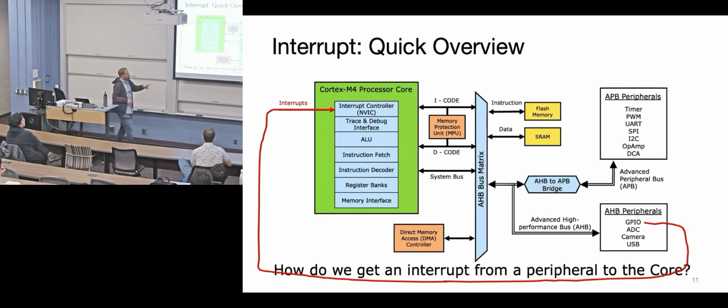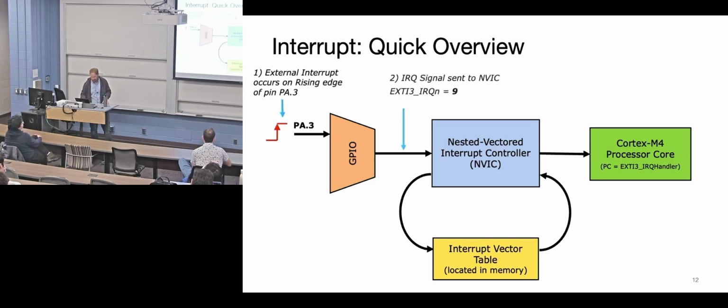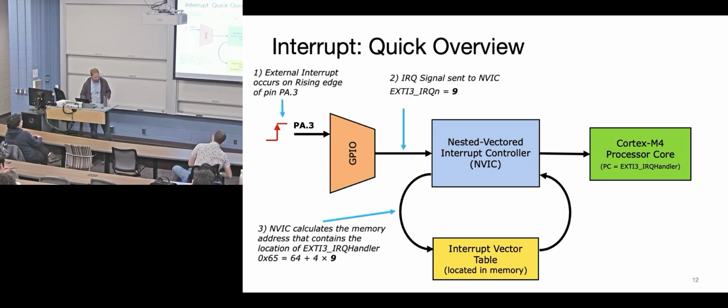There's only one shown, but all these wires come into the NVIC, and it does the lookup between the incoming GPIO pins, the interrupts that could go high, and the location in memory of the address of the interrupt service routines. This is the basic, non-fancy pathway to figure out which location in the interrupt vector table those lines go to.